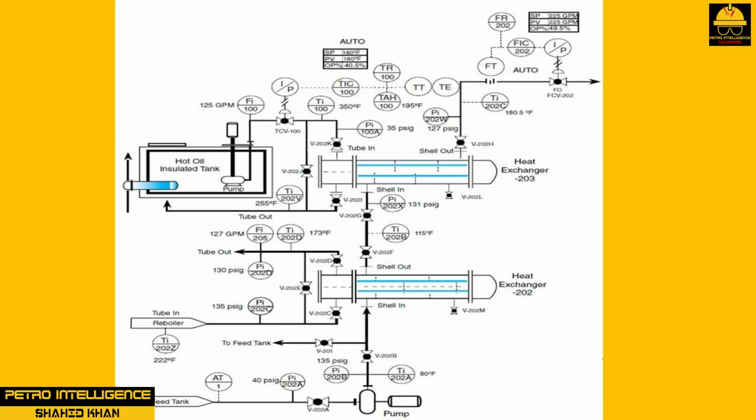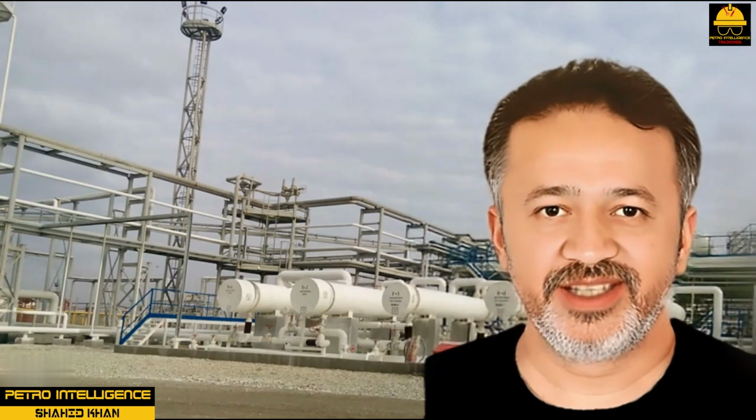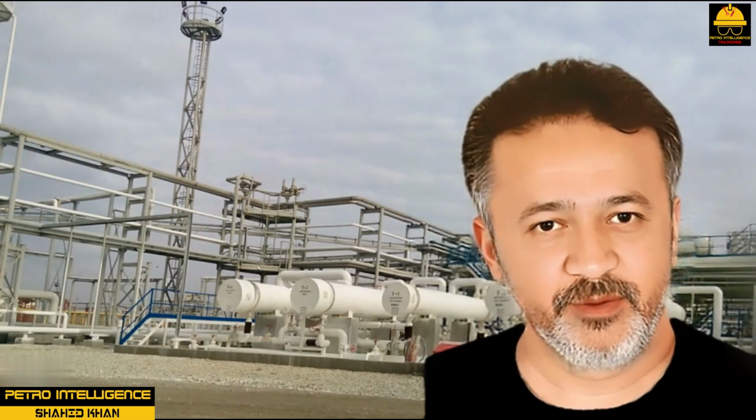A heat transfer system can be very complicated with modern process control instrumentation. Since a heat exchanger can explode like a bomb, proper training and care are needed during operation as well as startup and shutdown. This picture illustrates the various components found in a heat exchanger system. A flow control loop is found on the shell outlet of X203 and fails in the open position. This will prevent the feedstock from overheating and potentially rupturing the heat exchanger. Correct lineups on heat exchangers are essential, and process technicians should carefully review the standard operating procedure.